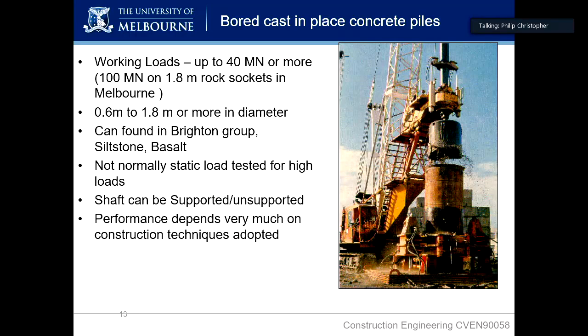So what we run through now, and you've already had some of this talked about, at least from a conceptual level, but in today's talk I'll talk also about the capacities of these systems. So bored piles, think of bored piles as we're just digging earth out of the ground. We end up with a hole in the ground, we fill that with reinforcement and then concrete. That's really all a bored pile is. If we're dealing with sand or unsupported loose material, it's a hassle because it'll keep falling in the hole as we're digging the hole out.